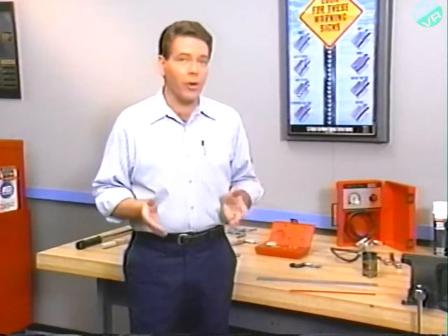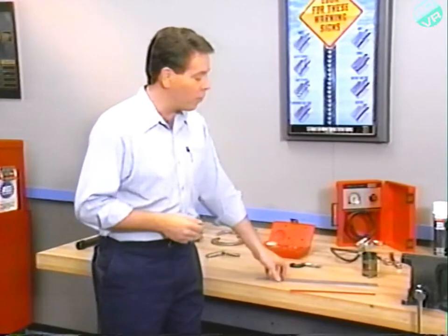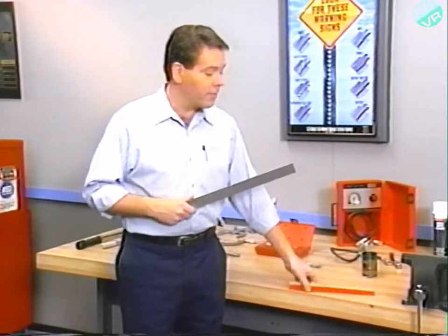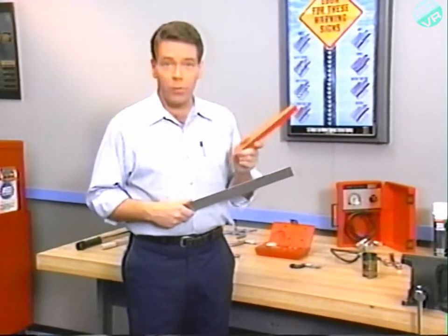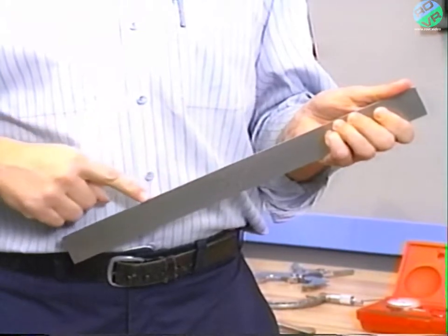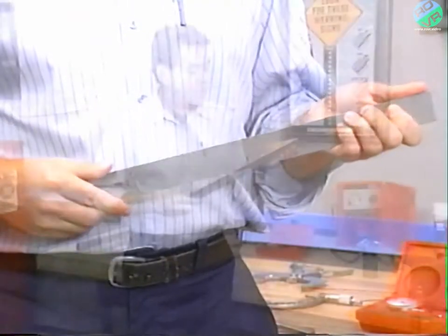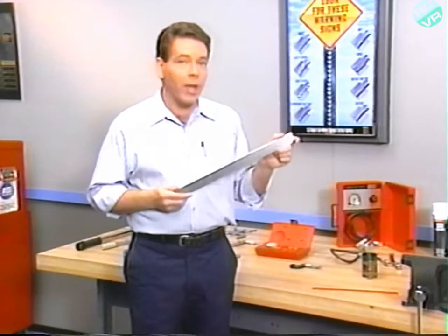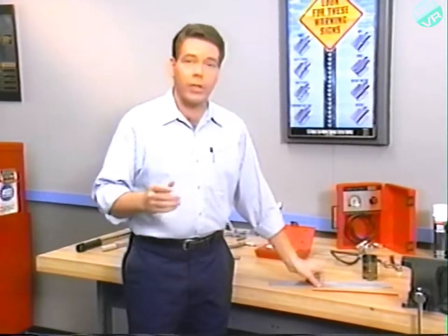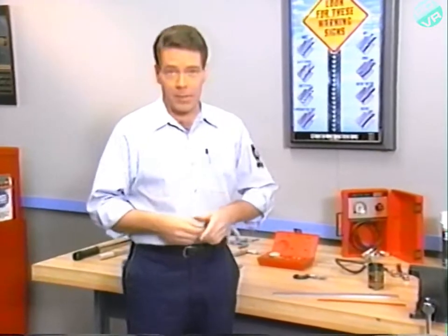To check cylinder heads and engine block surfaces for warpage, you'll need a precision straight edge. In this case, you can throw away your 1-foot wooden ruler. The straight edge is a steel bar with precision ground edges. It needs to be at least as long as the cylinder head itself, if not longer. Be careful when handling and storing a straight edge. It must not be damaged.